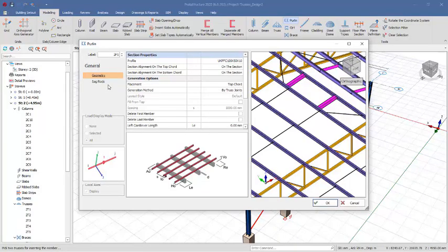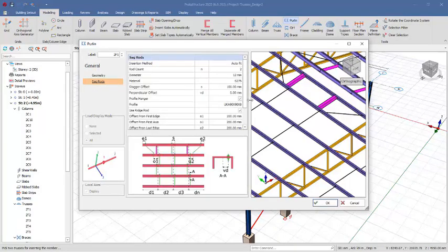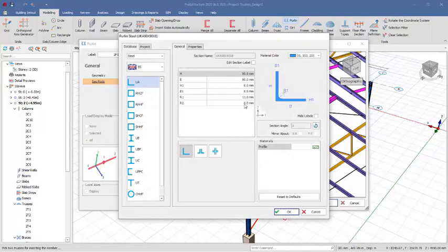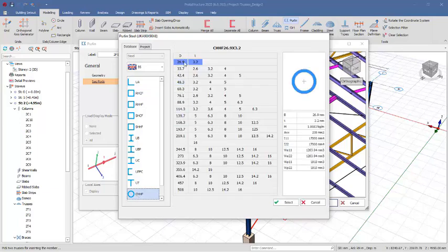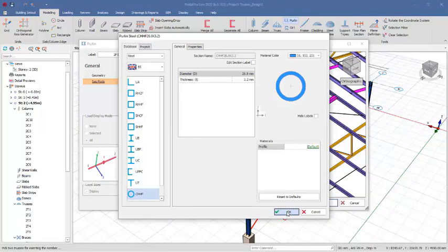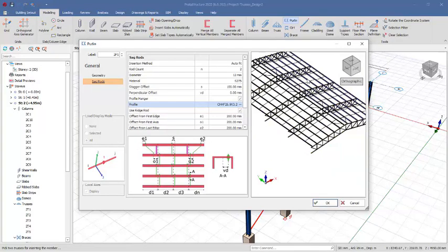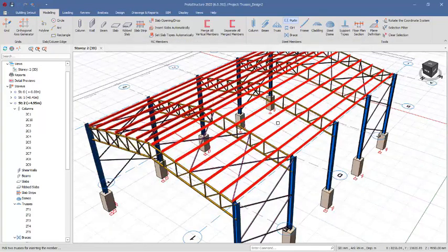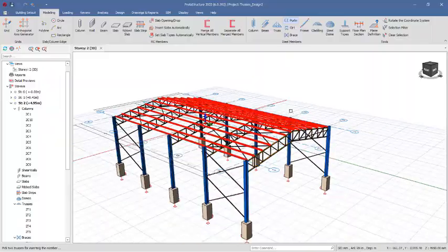bracing rod. Okay, so we'll go to the sag rod right there. We really don't want to use an angle iron, so we change the profile from a universal angle to, or maybe we'll be using pipe, this one. So we select the least one, which is 26.9 by 3.2 thickness. Right click on the select options and OK options to have this just like this. So after we click on the OK options, you have your purlins being generated just like this.